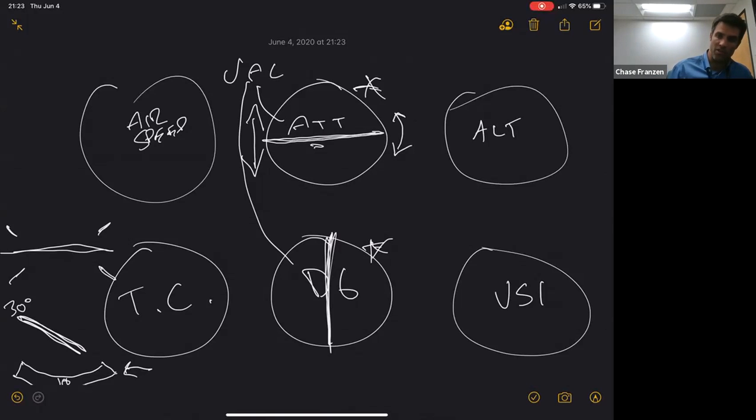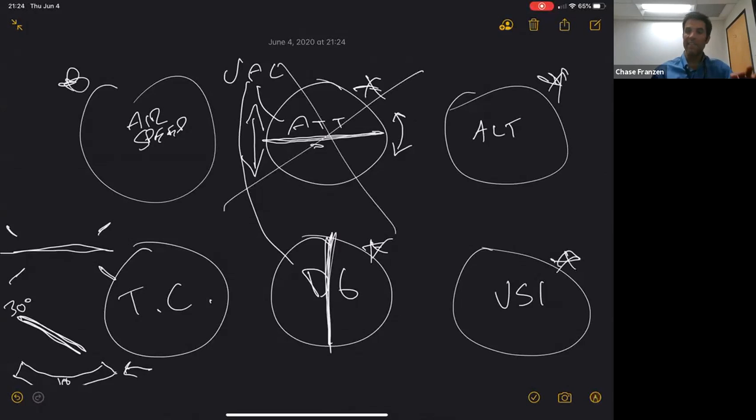The turn coordinator portion, the rate of turn portion, is powered again via electronic gyros. So that's the turn coordinator system, which again, if your vacuum fails, you lose your attitude indicator. Your turn coordinator is giving you a lot of the same indication. It's not giving you any pitch, but you can get pitch from airspeed, altitude, and VSI, but it continues to spin because it's electronic. It's giving you bank indication. So your attitude indicator might fail, you're in the clouds, but you've still got your bank indication from your turn coordinator. You know when your wings are level. So really quite ingenious, redundant system here.